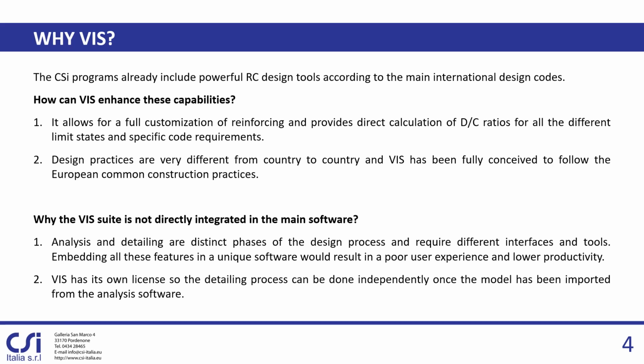The second answer that we have for this question is more practical, and it is the fact that VIS has basically its own licensing system, so the detailing process can be done independently once the model has been imported from the analysis software, and so the license of the main software, whether it is SAP2000, ETABS, or CSiBridge, can be used by others while we are performing the detailing part in the VIS program.